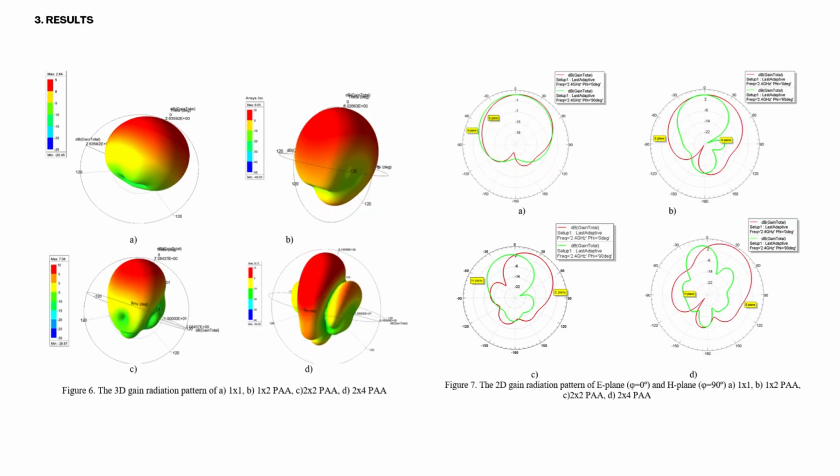Using a 3D polar plot, we can visualize how the antenna emits beams in 3D space, whereas a 2D plot is useful for accurately defining directivity and angles of emission, since it represents a cross-section of the 3D pattern. The 2D radiation pattern of the SPA is characterized by a half-power beamwidth, HPBW, of 83 degrees. It's shown in Figure 7a, indicating the angular span within which the radiation intensity drops to half, minus 3 dB.